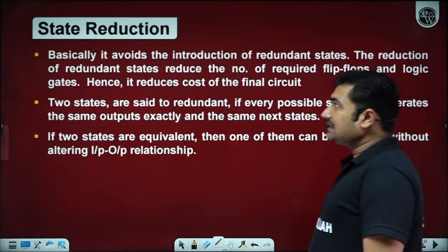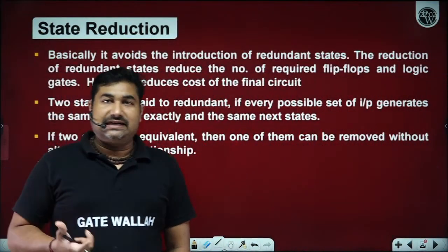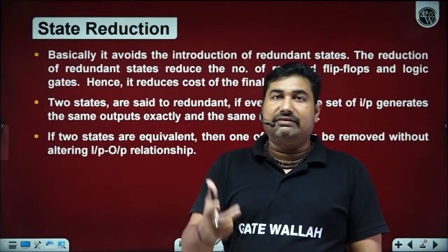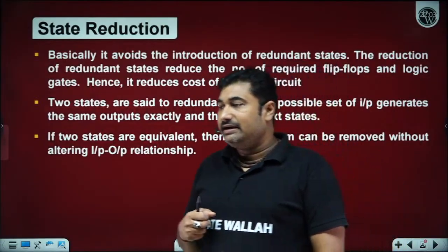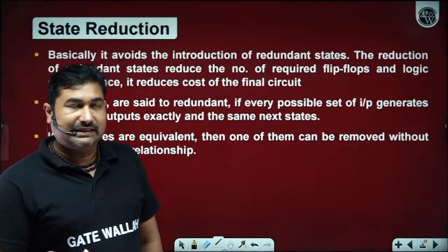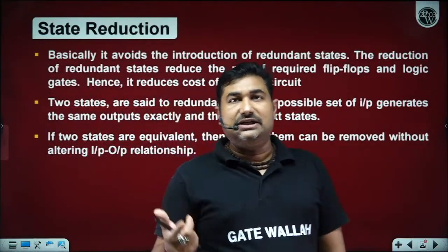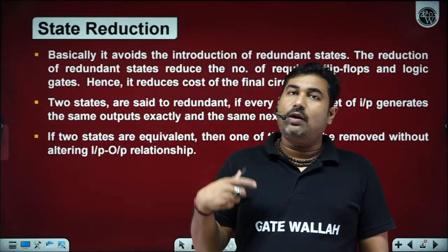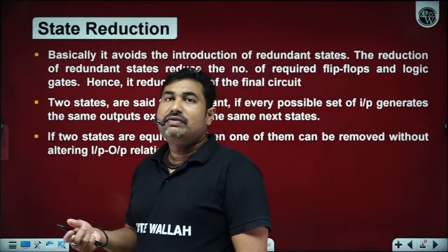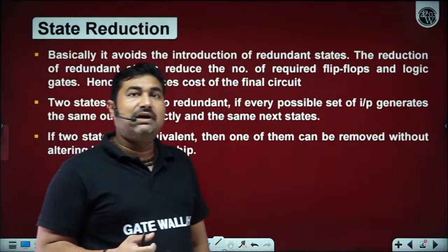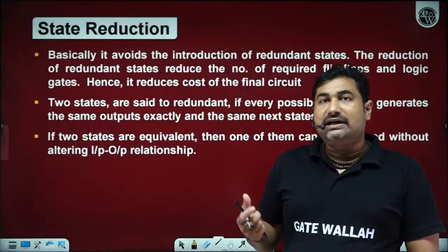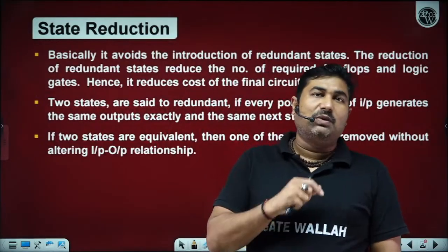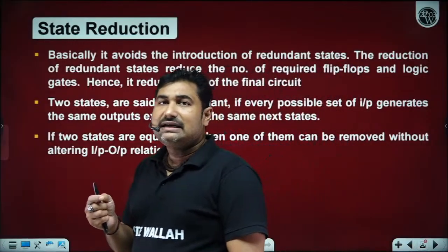Now please observe, first, state reduction. Why do we need state reduction? Whenever a user comes to the designer and asks to design some desired circuit, then as per his condition, there is a possibility that for the same input, the same next state and the same output may appear. We will examine this in the state diagram, and then we can remove the redundant state. If two states have the same next state with the same input and the same output, then we can remove one of the states. Is it okay?